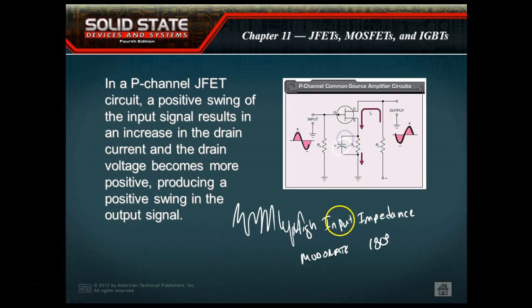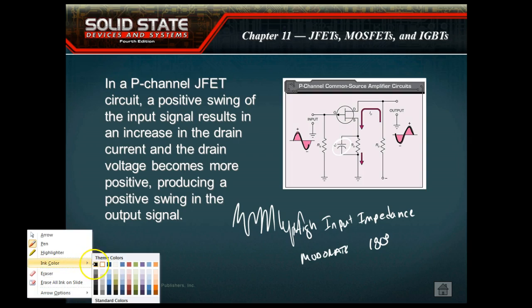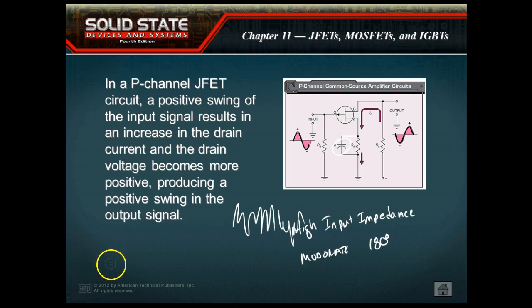This is still called a bypass capacitor. We would still bring in our input. Normally, since we don't have any DC bias on the input, we literally do not have to have a coupling capacitor on the input, which is another advantage. Now over here, this is going to be biased, so it's going to be sitting at a DC level, depending on what size we choose for RS. So that means on the output, we would have to have a coupling capacitor over here. So these are still called coupling capacitors.